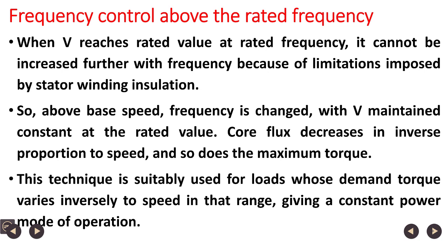Now, frequency control above the rated frequency. When V reaches rated value at rated frequency, voltage is the rated voltage, and if the speed is to be increased above the rated speed, frequency has to be increased above the rated frequency, but voltage cannot be increased further with frequency because of limitations imposed by the stator winding insulation. V by F ratio requires that if the frequency is high, the voltage should be high. At rated frequency, voltage is rated.